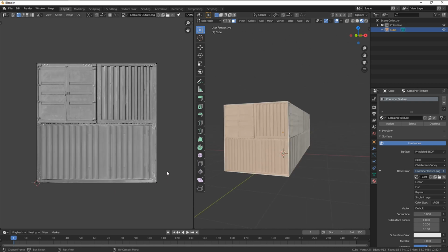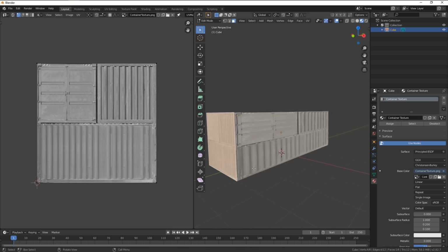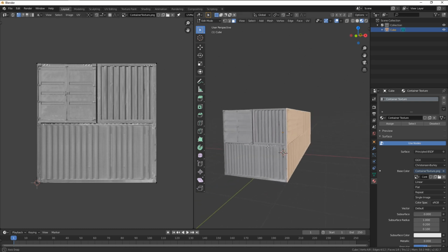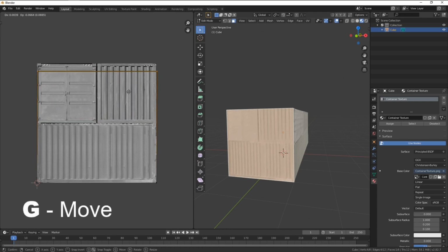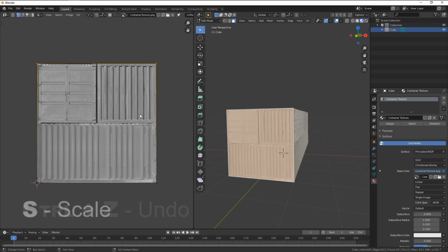What this has done is taken each face and, like the name suggests, projected the material onto it. So if we select just one face, it will highlight it on the UV editor window. We can adjust the projection using the vertex points. You can use the icons up top to change from vertex, edges and faces, with move, scale and rotation as you would in object edit mode.